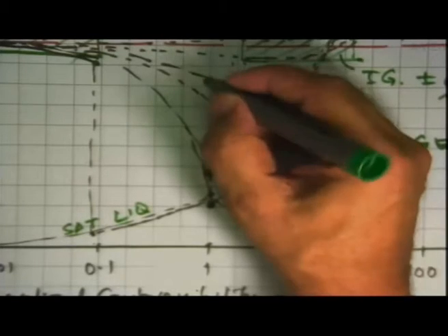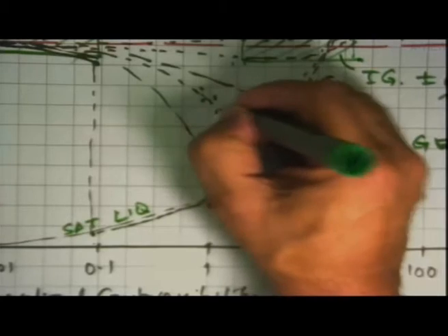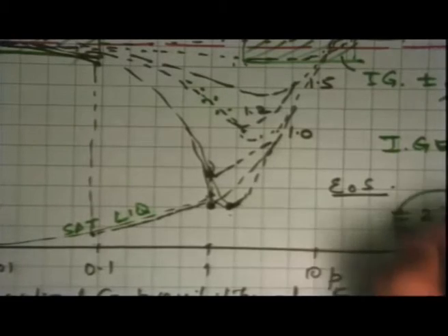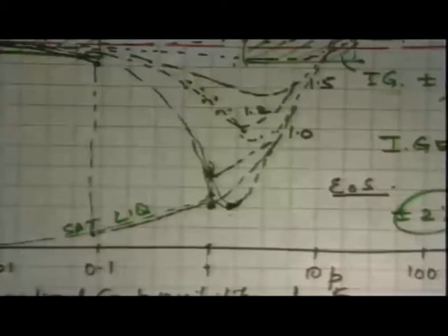on the critical pressure. And fortunately, what that does for us is that you get a very nice single compressibility chart for all materials. It's not that everything is lying exactly on this line. There is a variability around this from substance to substance, plus or minus 2% type of variability in making the generalized compressibility chart in the first instance.